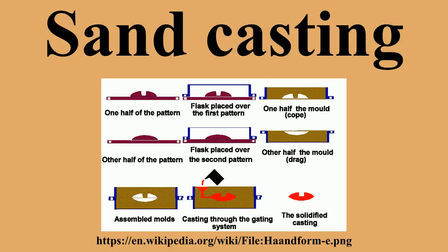Automatic high-pressure sand molding lines. Increasing quality requirements made it necessary to increase the mold stability by applying steadily higher squeeze pressure and modern compaction methods for the sand in the flasks. In the early 50s, high-pressure molding was developed and applied in mechanical and later automatic flask lines. The first lines were using jolting and vibrations to pre-compact the sand in the flasks and compressed air-powered pistons to compact the molds.